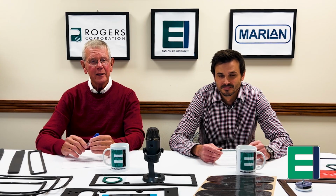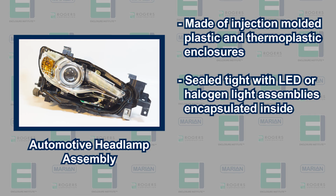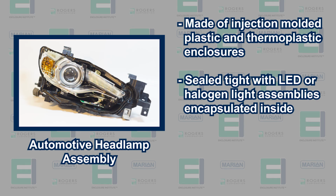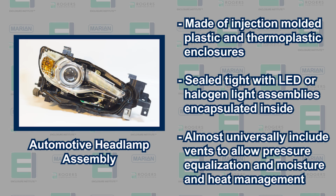But light assemblies in today's automobiles are made of injection molded plastic and thermoplastic enclosures sealed tight with LED or halogen light assemblies encapsulated inside. They almost universally include vents to allow pressure equalization and management of moisture and heat. The vent in the headlight assembly works like my new and very expensive rain jacket. It allows my body's heat and moisture to escape while keeping me dry from rain.